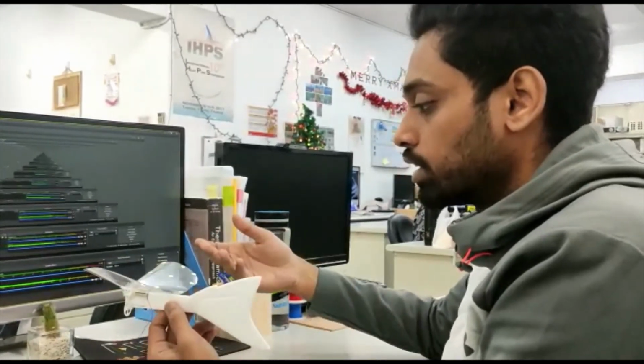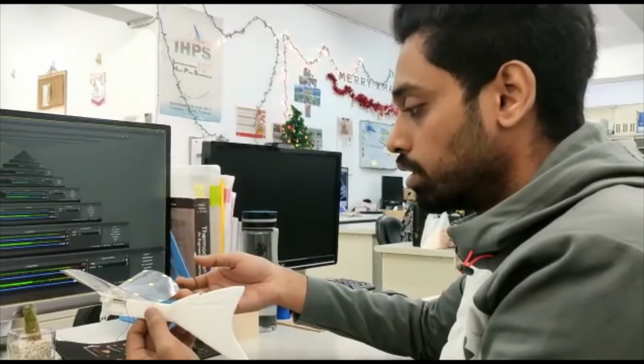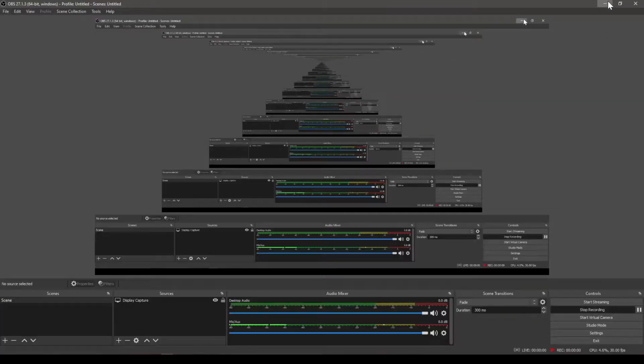Now the post processing, as I mentioned in the last video, we have to do in another software, and this is our wind tunnel. We have the calibration frame, so we considered the wind tunnel external boundary as the calibration frame for the post processing, and we have used LED as markers, so it is bright, and when we take the video from a high-speed camera, it is looking bright and clear, so that we can select each control point very clearly.